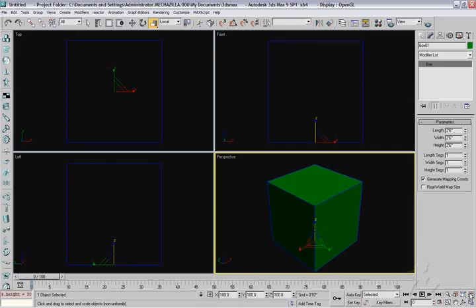Again, that's down in the lower right hand corner of the program under the viewport tools, and it's the 3D cube with the 4 red squares behind it. Go ahead and click on that. Once you've clicked on that and it's all centered up in all 4 viewports, one of the things in the idea of box modeling that we try to do when setting up in advance is think of the concept of what's called pre-segmenting. The idea here is that we want to create enough segments in our object